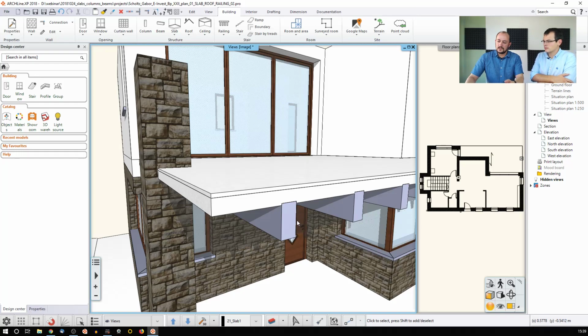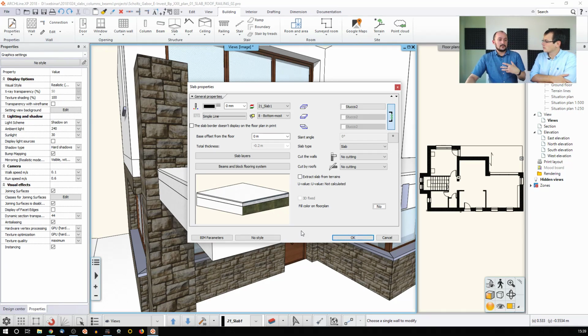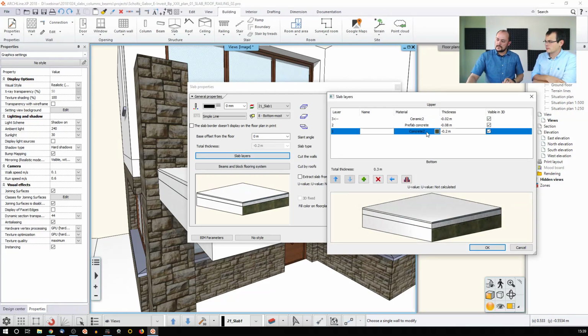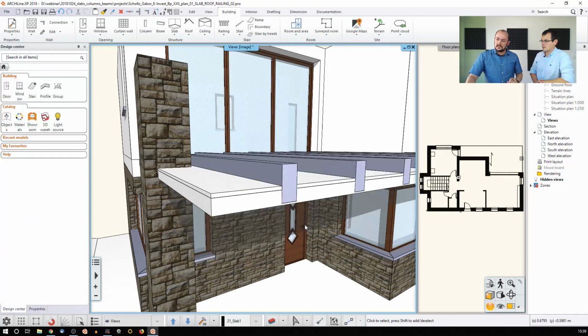There is also another way, which I think is much better, and it describes how this whole inheritance works inside the structure. If I'm actually erasing that layer, so instead of disabling it, I just select it and erase it, what happens? Should the beams disappear because I have erased those layers, or do they just move somewhere else? Actually, the latter will happen. They automatically jump to the following layer. So the software won't destroy what you have created. It just tries to find a better position.